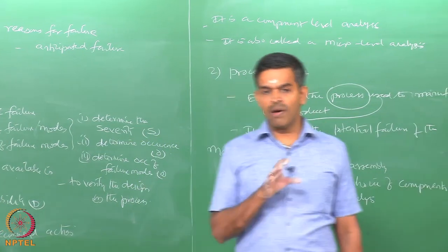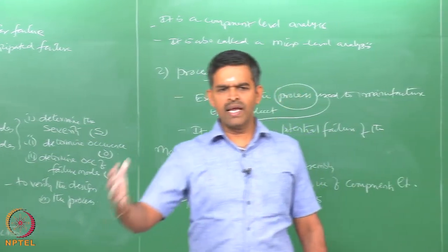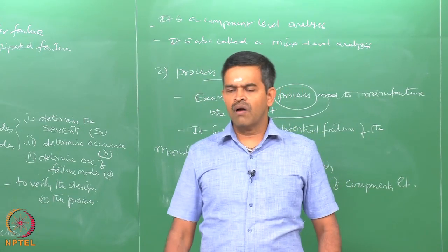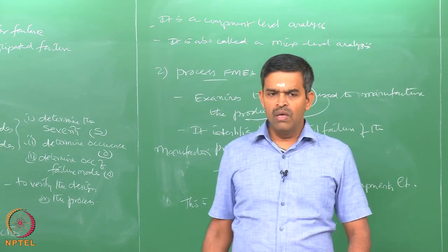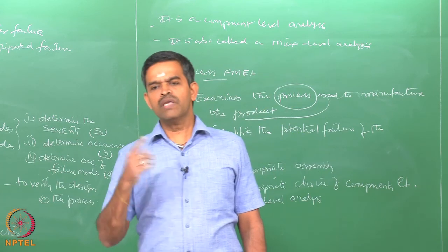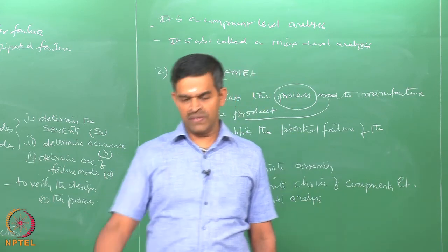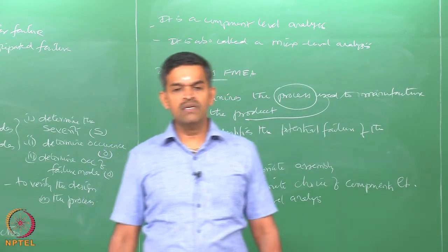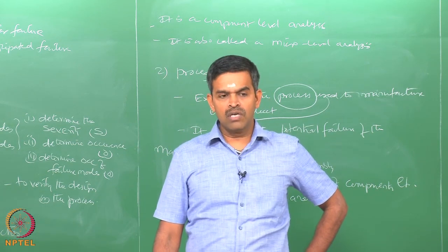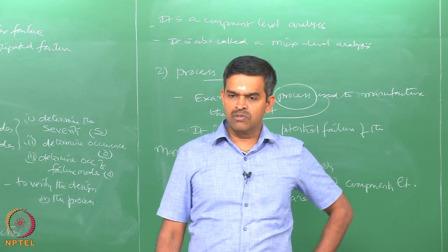Then try to identify the components of BOP and do an FMEA analysis and see amongst the components present in BOP or a drilling stack as a whole, which is the most vital and critical component. This will give you a very good insight of understanding the whole process, which would lead to an accident. Once your understanding about the process is clear, I am sure you are contributing towards the safety assurance to the maximum level.